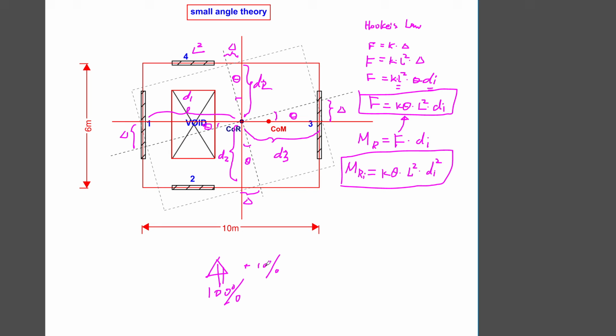It's resisting this 10% eccentricity torsion, right? The 10% eccentricity torsion, let's call it Tm. You can work it out by the equivalent static method, and by doing torsion analysis, you get your torsion moment. I'm going to make up a number here, say 100 kilonewton meters. That's your torsion moment, induced by your 10% torsion.